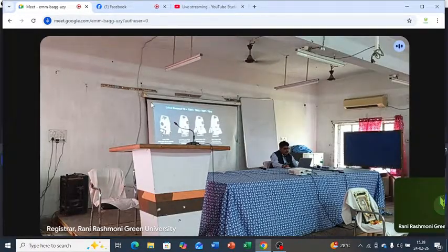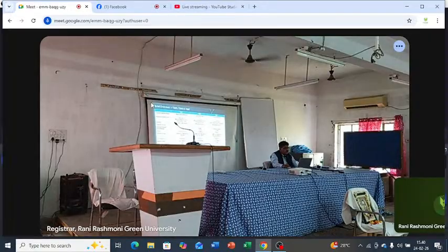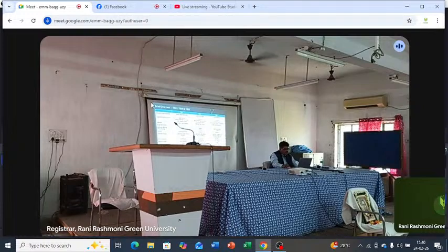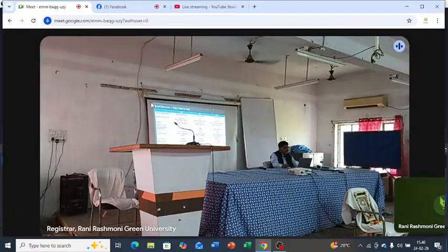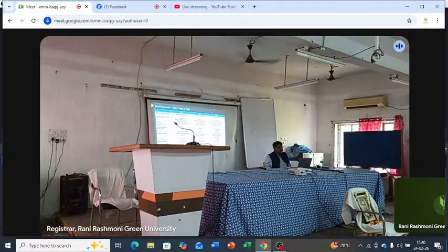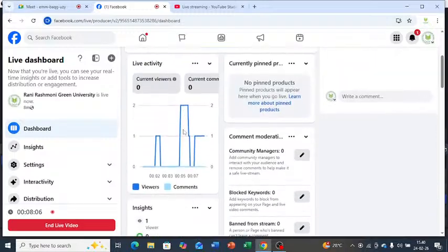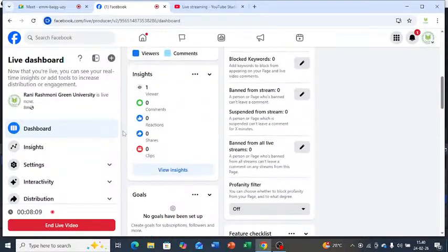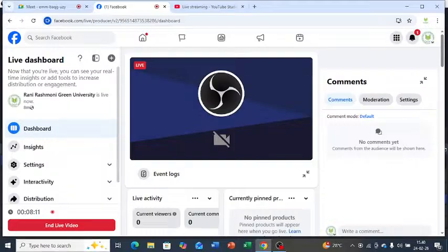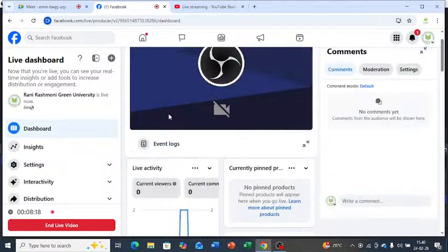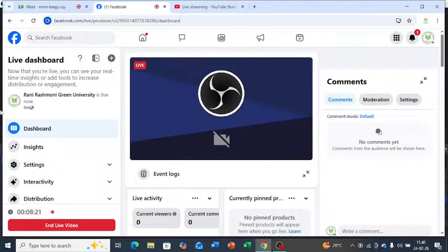Now a little more detail on the manual total stations. You can see the comparative specification differences, but one thing that stands out is that under PA07 you have a reflector-less range of 1 kilometer. That means you can measure to any object which can reflect light up to 1 kilometer without any prism. It can take measurements from a branch of a tree, or the rock surface. So without having gone there, 1 kilometer away, you can still take a measurement. Others can take it only up to 500 meters.